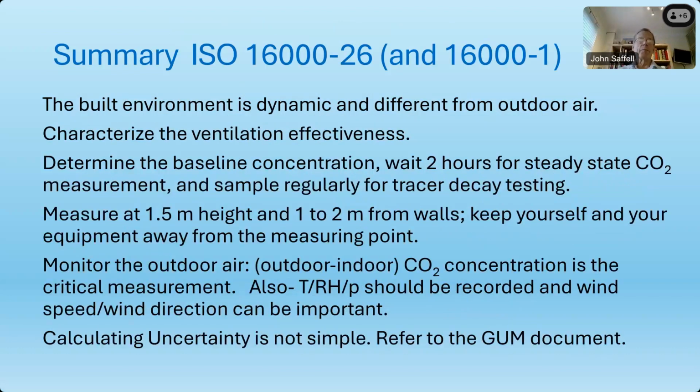So in summary, the built environment is dynamic and it's different from the outdoor air. You must characterize the ventilation effectiveness, and importantly, start by determining your baseline concentration. Wait for a couple of hours for steady state when you're measuring a steady state CO2 measurement. And when you're doing tracer decay, which I think is a better technique, then you need to sample regularly.